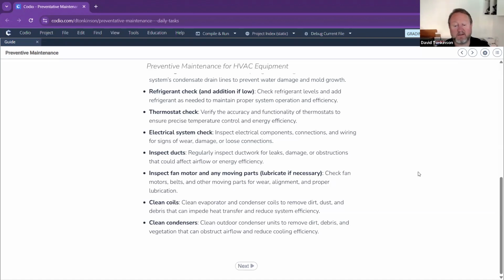As with everything else in our data center, a visual inspection, check the electrical system's okay, inspect the ducts to make sure there are no eggs basically laying in there, no birds decided to nest in any of your ducts. And inspect the fans to make sure that things are moving, everything is lubricated properly, and there's no shaking in any of those items. Again, it's another case where we could potentially fit a vibration sensor on it to cover us. But if the vibration sensor is going to cost us a lot of money, well, we should just be able to physically go and check it. That might save us some cash.